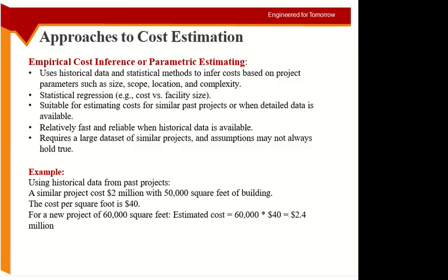And then we have the cost which is from the past data, historical data. So you have similar projects being done in the past, you get their cost, and again you calculate the rate, because your project may have a different area, may have a different size. So you go back to the old projects, but from those old projects you don't take the total cost, you take the rate of the cost. Okay, so per square meter or per day cost, something like this. And then using that you can calculate the total cost of your own project using the rate, not the total directly.